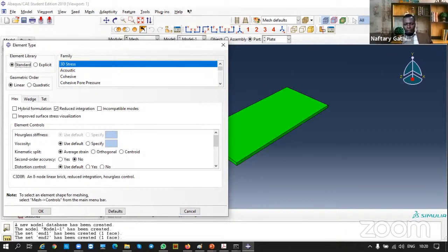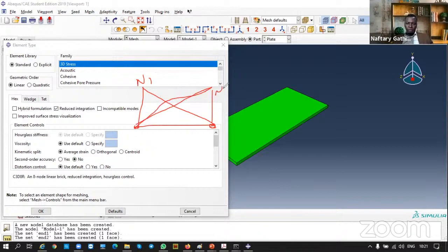There is a lot of learning here. If you remember when we talked about shape functions, we talked of a solid element with nodes, and the shape functions N1 and N2, straight lines. We said they are linearly varying in the case of the bar. When we came to the beam, you found that they were cubic.